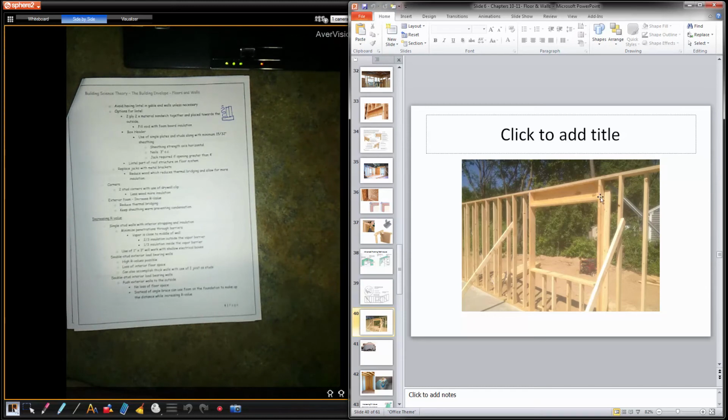You can see backing here. This company put backing for the exterior for probably a bigger trim. So maybe they're going to have a 3.5 inch trim on the exterior of the window, so they want to make sure there's nailing there. Again, nailing into sheathing is fine. They're really worried about the finishes. Then you're reducing your insulation.